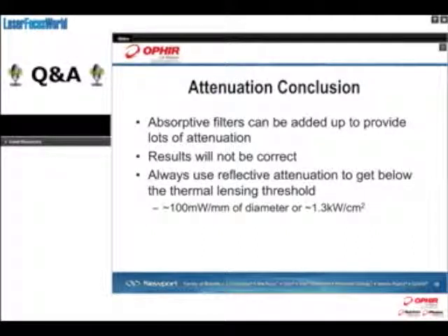And if the beam position doesn't wander off of the center of the profile, then you know you're parallel. So if you move through that waist caustic and watch the position, as long as you don't move more than your limit for how parallel you want it to be, you can tell that, if it's in the same place 5 millimeters in front and 5 millimeters behind the waist, then it's going to be parallel through the waist.